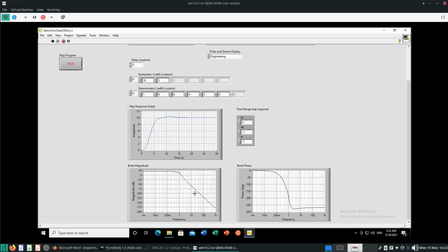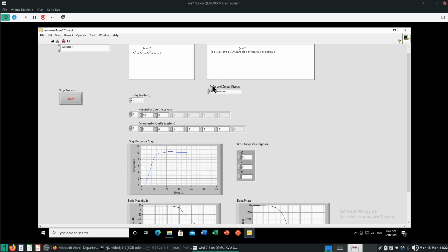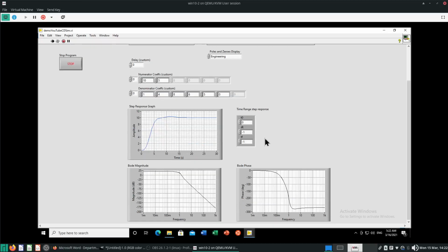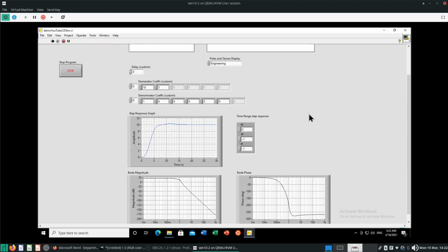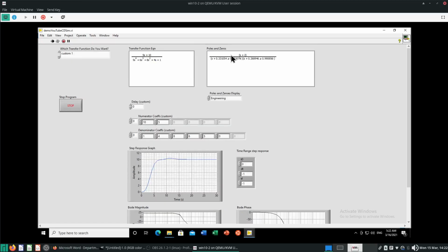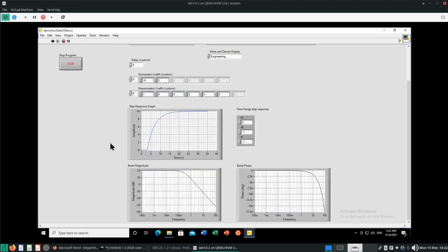Okay, so do we see that happening here? A bit hard to see. Yeah, it's very hard to see, but we do see the downward slope at around 1. So it's on the order of magnitude of 1 that this Bode magnitude plot actually starts to slope down. So this tends to be okay, not too bad. Seems legit, at least.